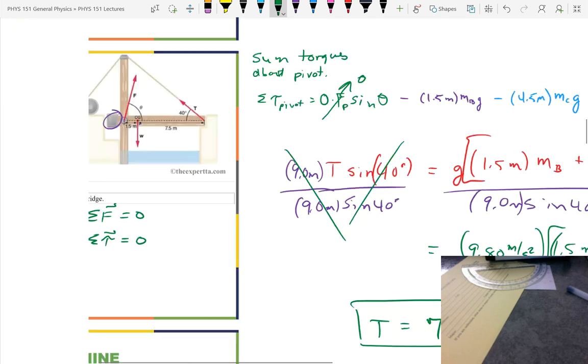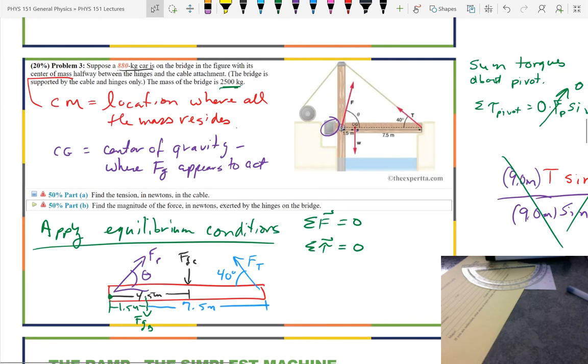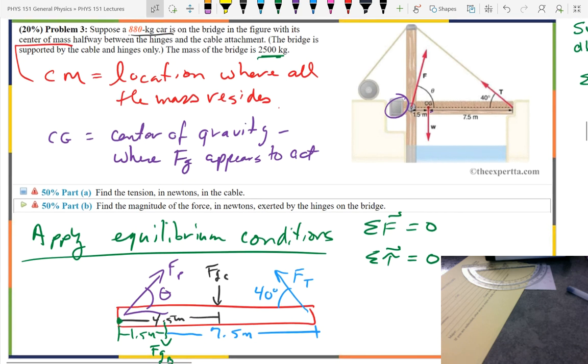Now, like I said, life suddenly got a lot harder when we got to this slide, didn't it? So what were the steps I used in solving the problem? What was the first thing I did? I trust that you said showed, and showed was the word I was looking for. I showed my rigid object that I was interested in and all of the forces acting on it at their location. So I indicated the position, the angles, the forces. That was the first step for an equilibrium problem.